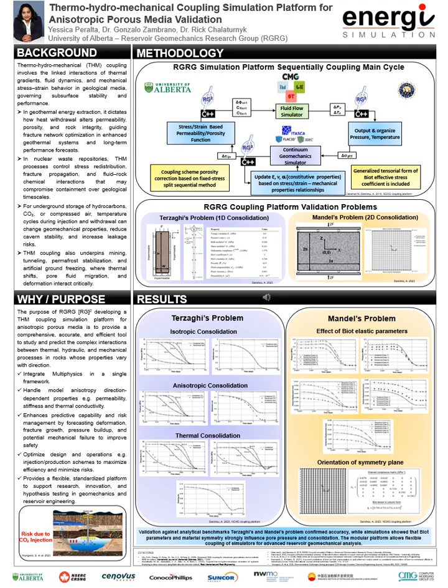This is important because in anisotropic materials, pore pressure can also induce shear stresses, not just hydrostatic effects. These stress increments are applied in FLAC3D, which then computes the mechanical response of the reservoir under drained conditions.